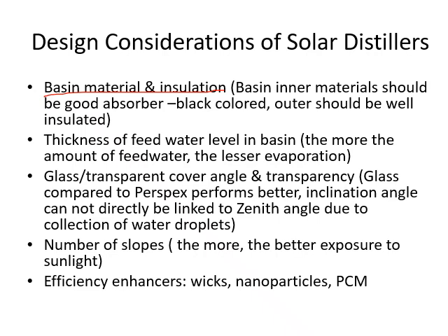Right? And the thickness of the feed water level is very important. A normal design is like 2 centimeters of water depth, which is good enough in the basin. Beyond 2 centimeters, it has been reported that most of the solar thermal energy is used up just to increase the water temperature slightly, because water has a high specific heat capacity, 4.18 kilojoules per kg Kelvin, to increase 1 degree Celsius of 1 kg water.